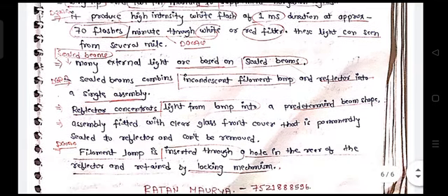And sealed beams are there. Many external lights are based on sealed beams, and the beams are all sealed, so that you cannot touch them with your bare hand. A sealed beam combines incandescent filament lamps and reflectors into a single assembly. The reflector concentrates the light beam and makes it focused.